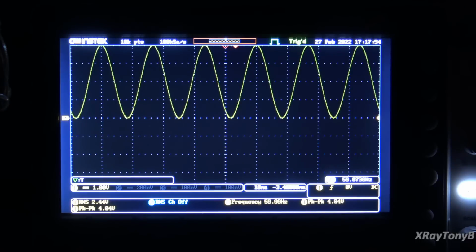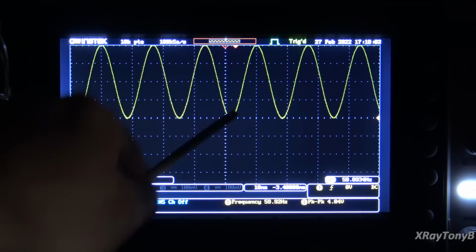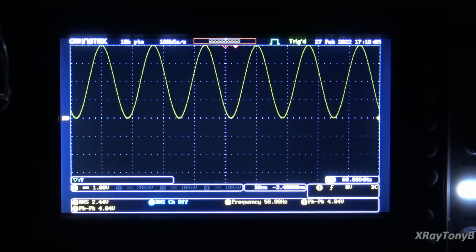But it's equally an accurate statement to say that this is a pulsating or a sinusoidal DC signal, because it never changes polarity. All right? Now, there's a lot that this affects. Knowing where your reference point, where the ground, where the common point is when you're measuring something is extremely important, and we'll learn that in future installments of this series. But I want you to get your mind wrapped around that right now, okay? What we're seeing right here.